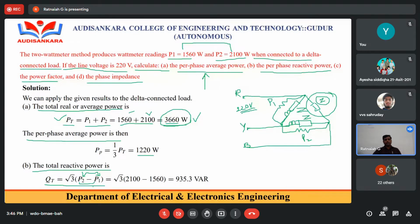So what is the difference of both the wattmeters? Here the P2 reading is more compared to P1. Therefore, I can take it as the more dominant value, so I take P2 minus P1. Then root 3 into this value, that means 2100 minus 560, gives 935.3 volt ampere reactive. The unit for reactive power is volt ampere reactive. This is the total reactive power consumption for 3 phases.